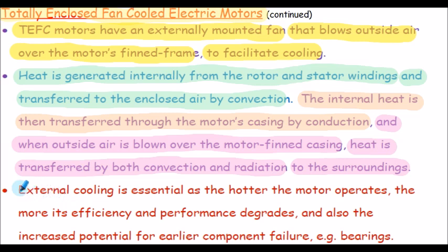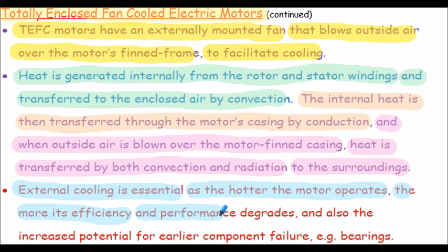This external cooling is essential for the TEFC motor, as the hotter the motor operates, the more its efficiency and performance degrades. And also there is an increased potential for earlier component failure, for example, the bearings.